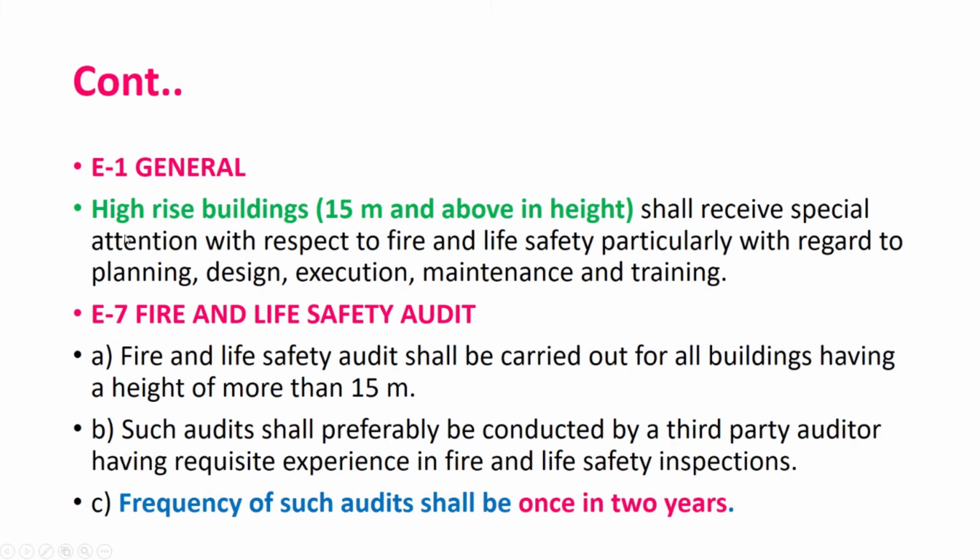Many times we provide FOBs without a cover on top, but now it has been reiterated that at the initial stage itself you should go for provision of covering over that FOB. The number of floors envisaged and their usage should be clearly mentioned in the general arrangement drawings of the FOB. Structural design should cater to the intended usage of the FOB. It is clearly written that in case you want to have a facility of a 2-wheeler or a 3-wheeler over it, then it should be designed accordingly.